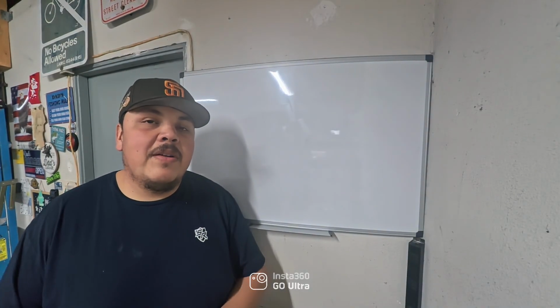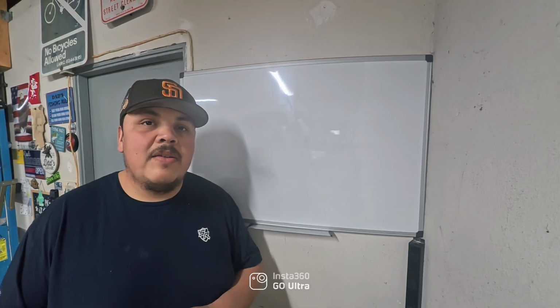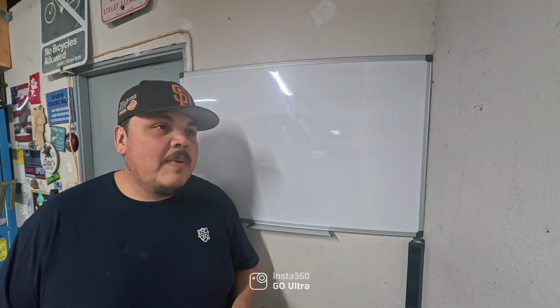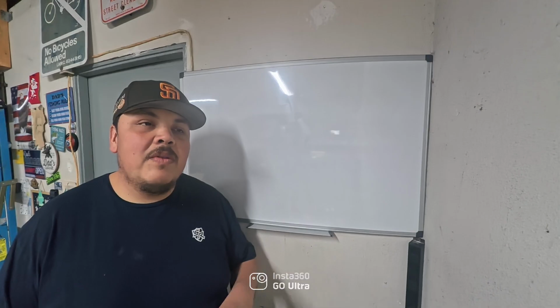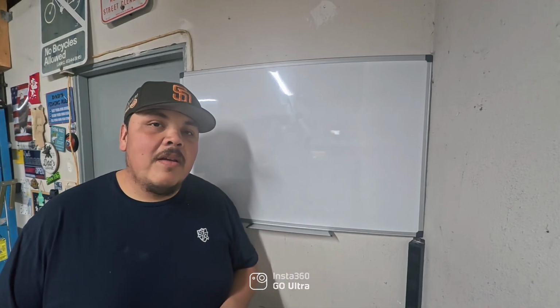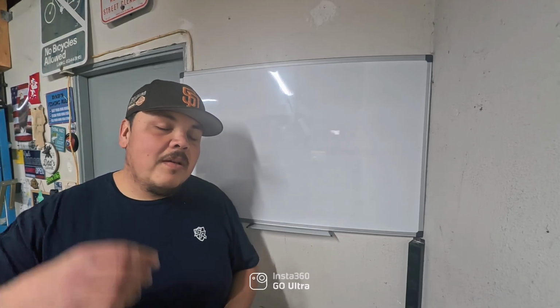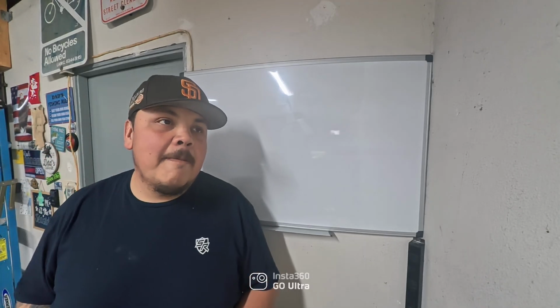So today I'm going to be talking about how I diagnose trouble codes related to the airbag system. Based on my experience, we have two common types of codes: one being resistance too high, and the other being short to ground. Those are the usual suspects that we see at Hyundai.